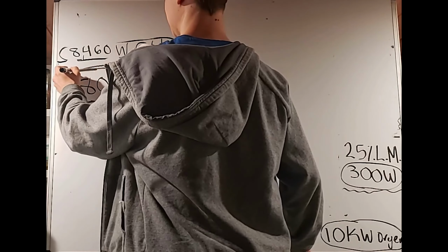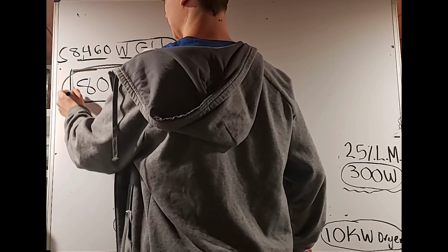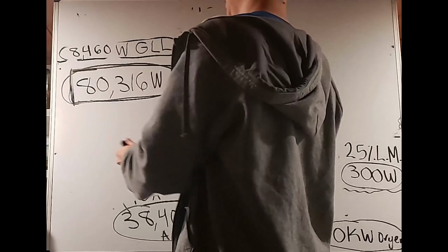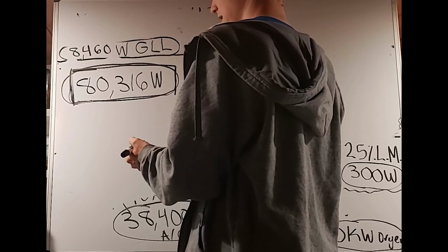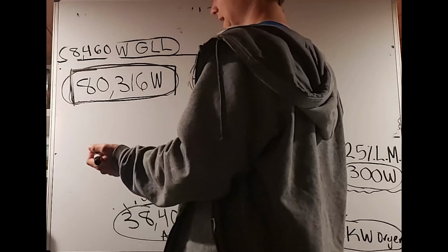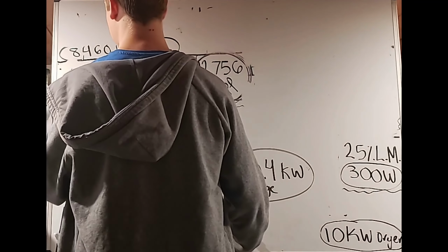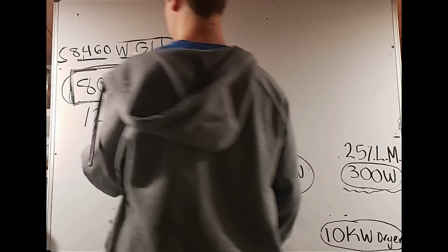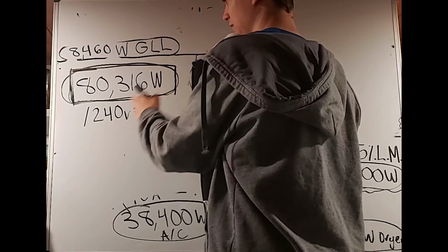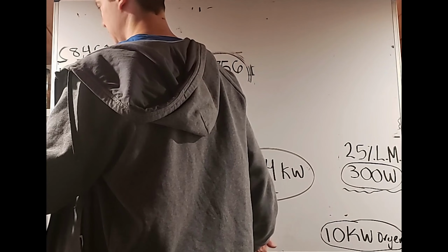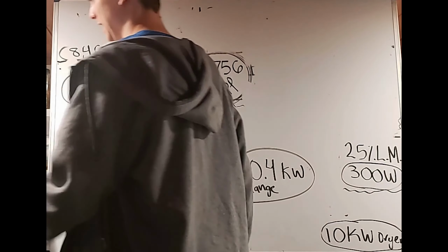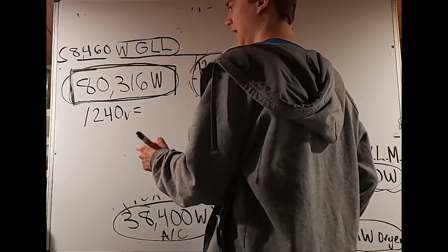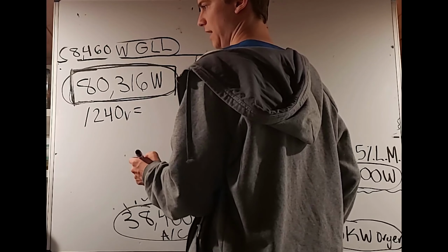So here, because this is the actual final wattage, in other words, the demanded load of this duplex, I'm going to have my square, so then I can look at this and see this is a final answer. But I also need to know that if I want to find my amps now, I'm going to have to take that and divide it by 240 volts. Of course, because we're working with volt amps here, watts, we're going to divide by volts, and we're going to get our amps. You are working with residential, but because we have the two-phase system A and B, we do have a 240 volt potential, and that is what we're using to divide by to find our amps. We get